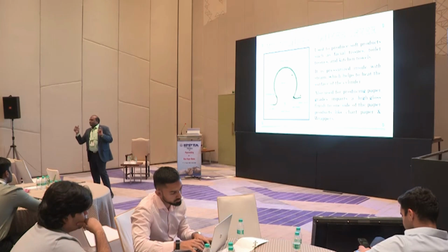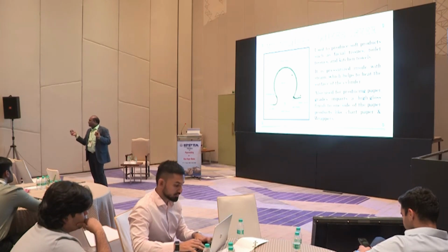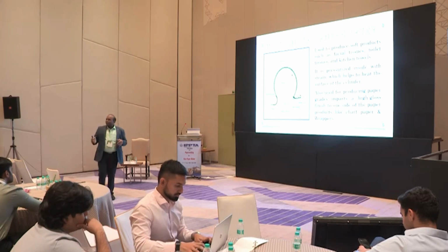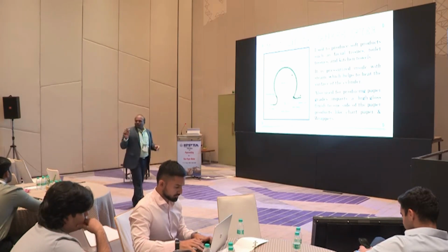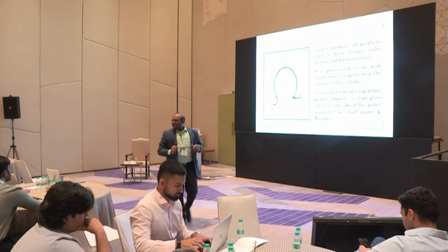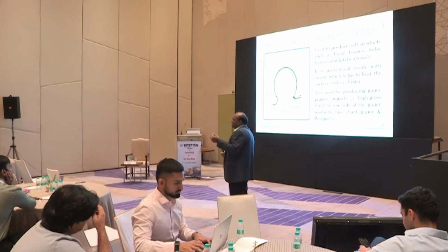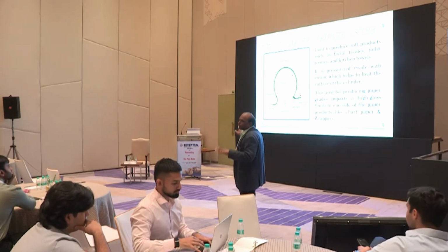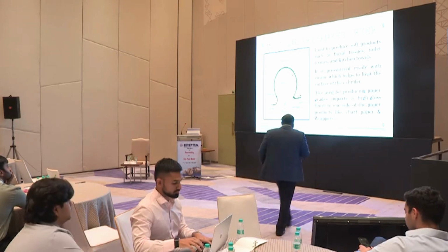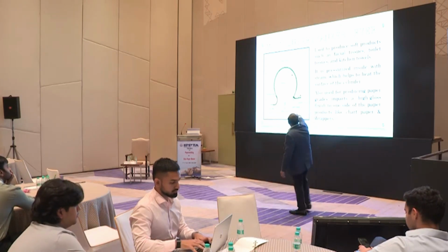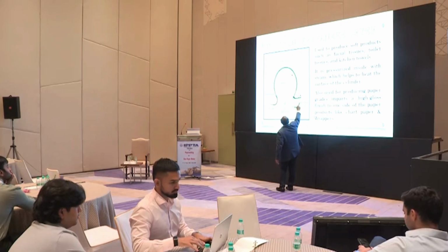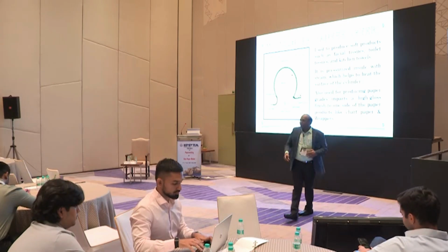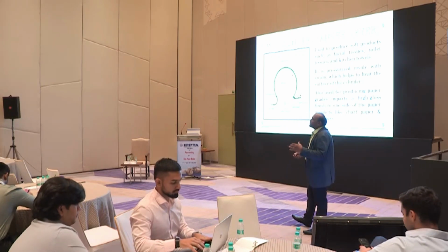And if your grammage, the basis weight, is very low, for example tissue papers or very low grammage like Bible papers, Bhagavad Gita, Quran, that paper is also very light, less than 20 GSM, and postal inland letters like that. These kinds of papers can be produced in this type of dryer section. That crimping I told you, sir, is here. The machine speed will be reduced after this dryer section, since the crimping process involved in tissue making makes the tissue paper softer.